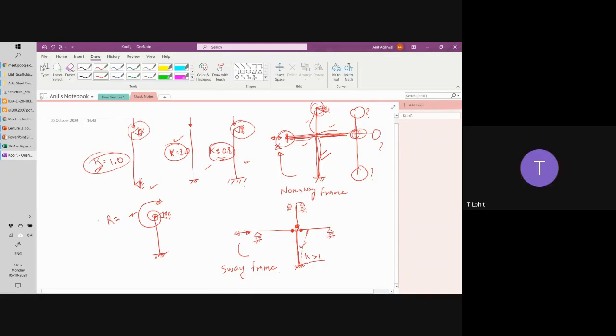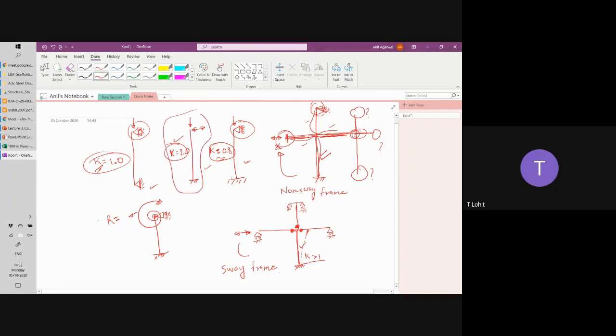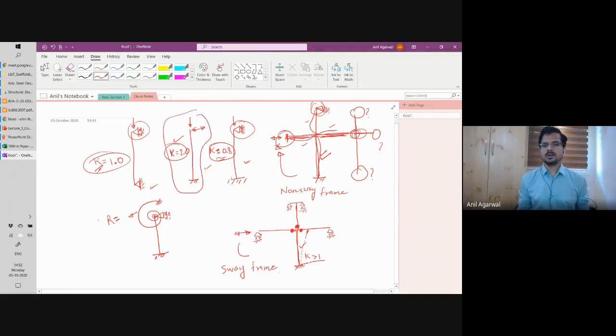2 only. It will be free cantilever. Then basically you end up with a cantilever only. Right? See, laterally it is free to move. As far as rotation is concerned, it is free to rotate. When it deforms, it rotates this way. This is also free to rotate because the three members connected to this column at this end are all pin connected, so they cannot transfer any moment. So K is equal to 2. That will be an ideal condition of K is equal to 2.